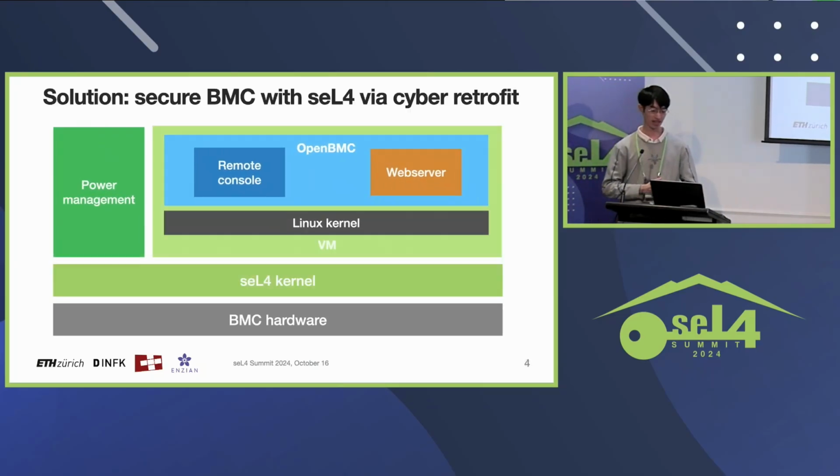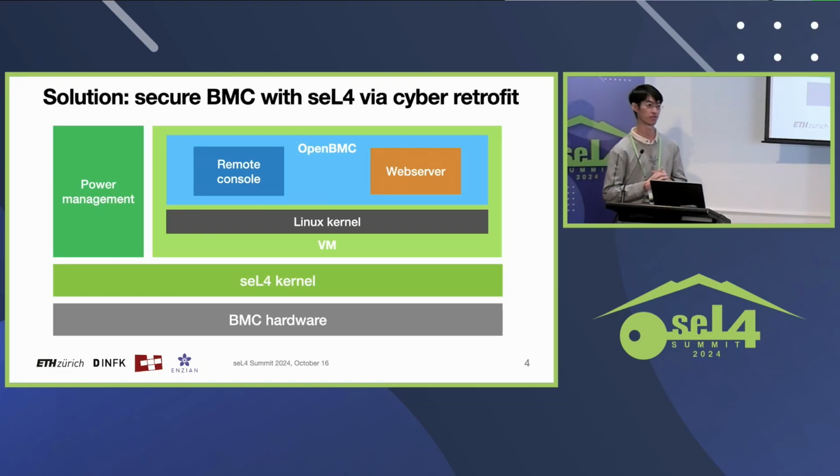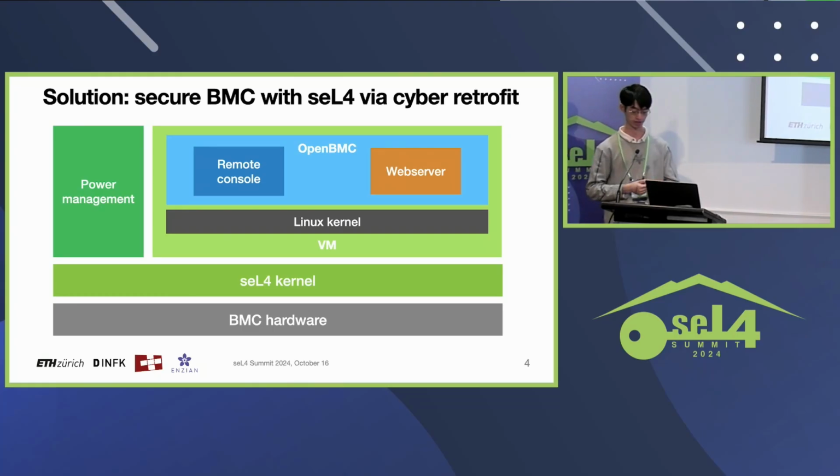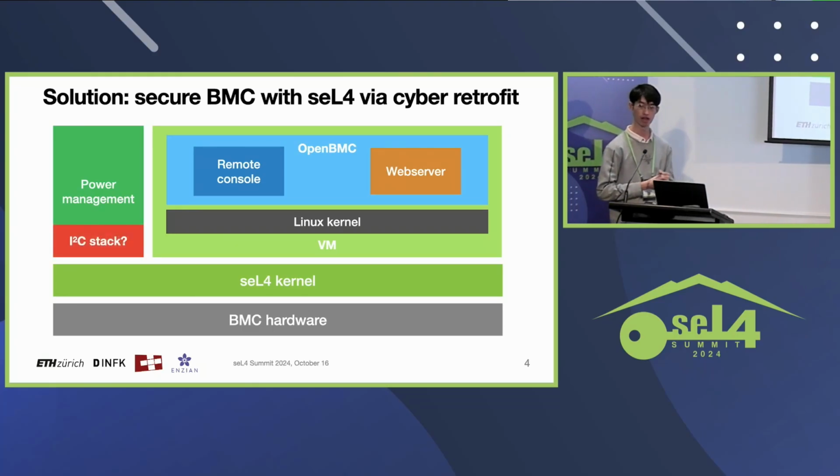So we apply a now pretty well-known approach, cyber-retrofit, to secure the BMC. We use seL4 as the kernel and run Linux and OpenBMC in a VM. And we extract the critical pieces like power management out into seL4 and retrofit them as a highly assured component. But there we have a problem. We have seL4 as the kernel, it's very secure, very high performance, but now we need to write our own drivers. And specifically, we are interested in the I2C stack here. How are we going to write